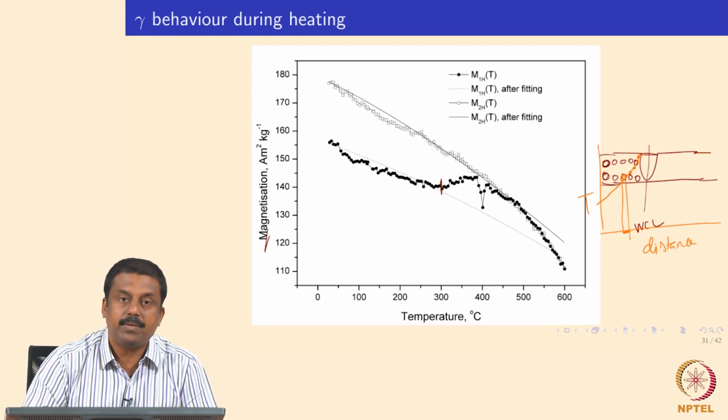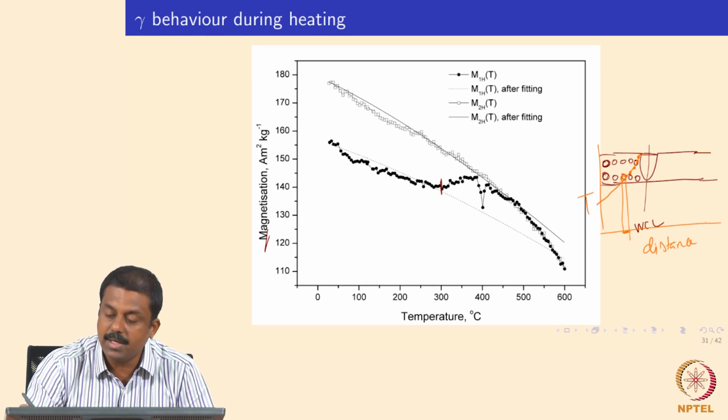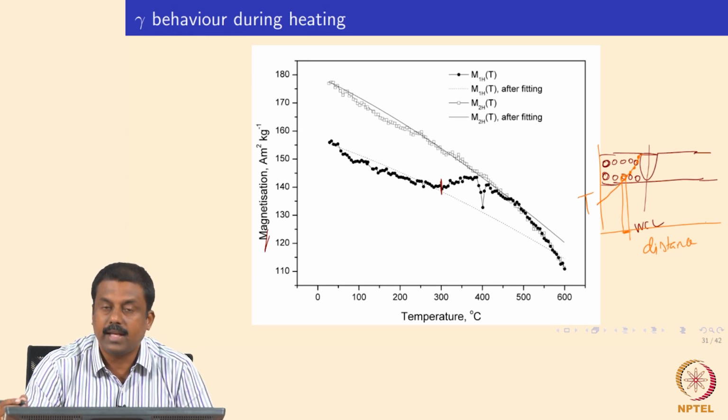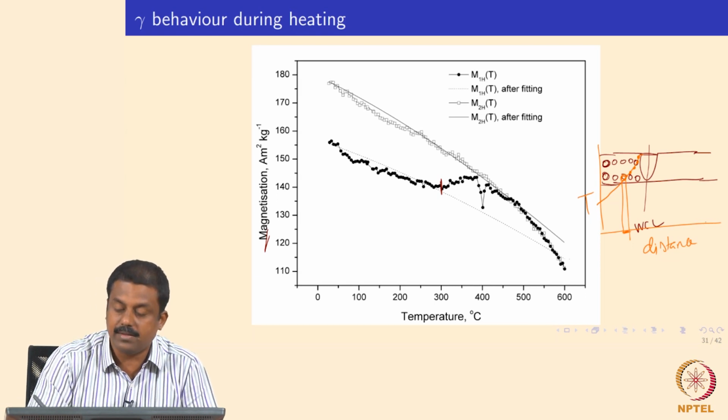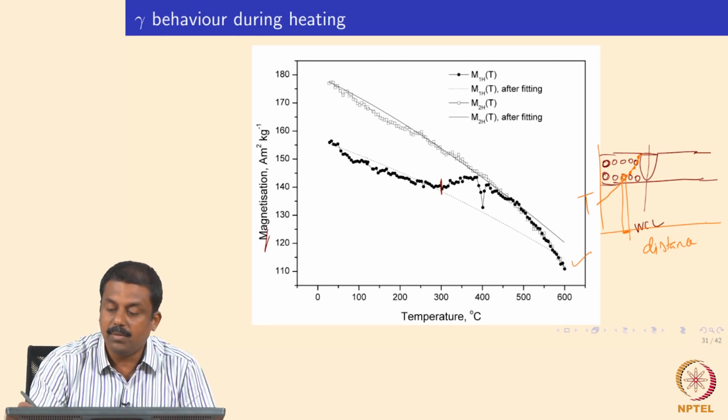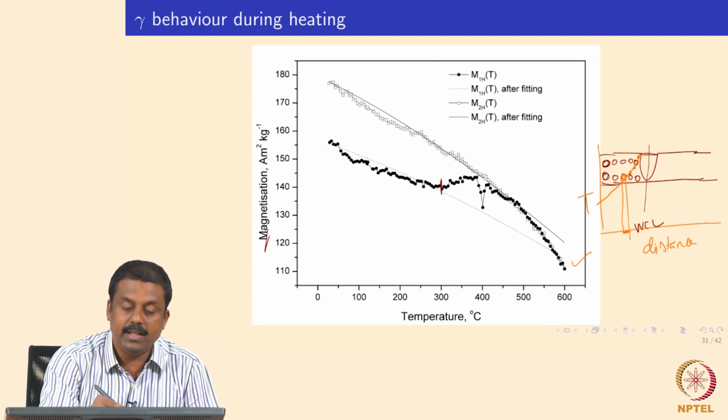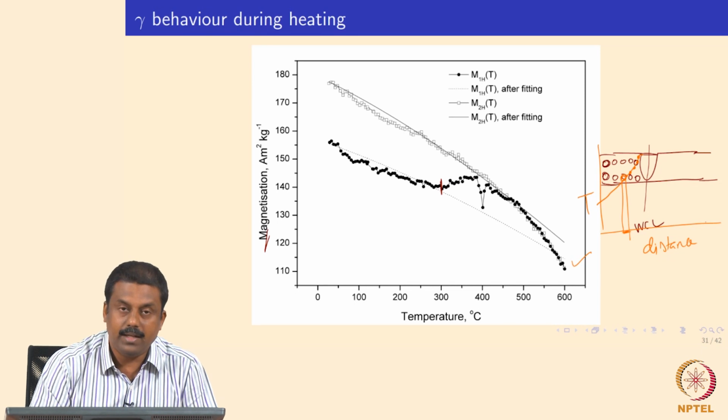Whereas in the magnetic measurements it is not possible, because we will have to machine out the sample with reasonable size in order to measure the bulk retained austenite concentration. It is very good to carry out measurements like in this graph. I showed you how to study the effect of temperature on the retained austenite stability.